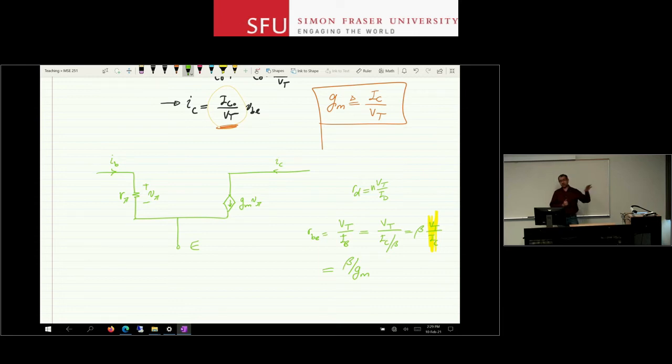So I calculate my small signal parameters, look at the output. I will see some change at the output. If I need to, I can add the DC part to it to make sure that everything is fine. But usually, no. Because in most cases, for DC values, you have well-defined parameters.